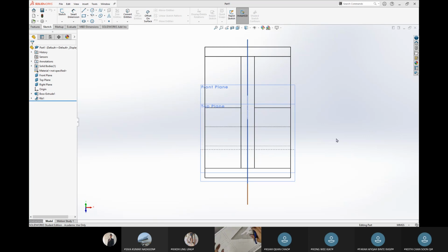So let's go to the front of the object. The front of the object is related to this line, so I'll draw one across. Okay, the next line. This is a hidden corner that is covered by the front. If you look from here, you won't be able to see this corner. So it's a dotted line.